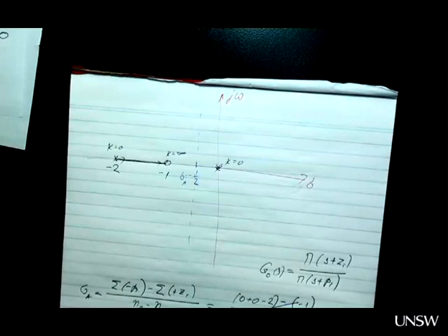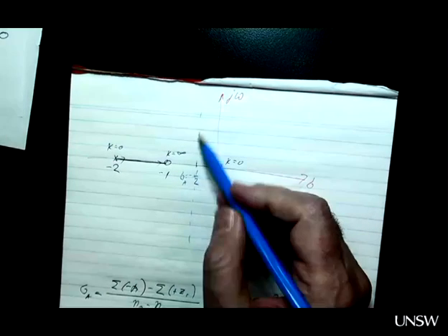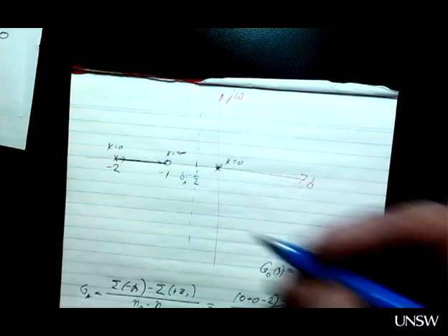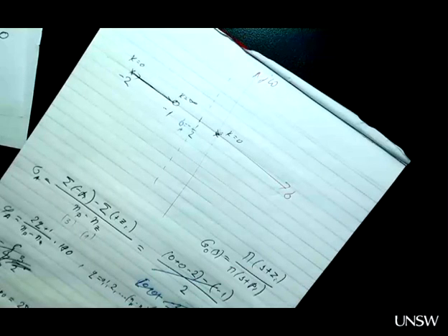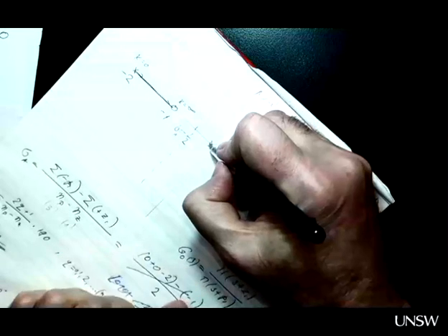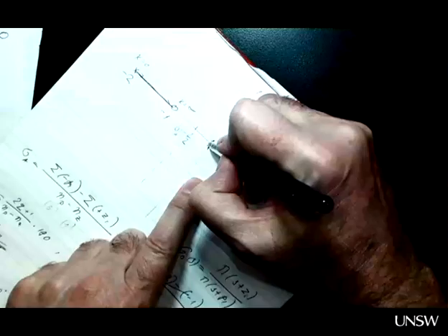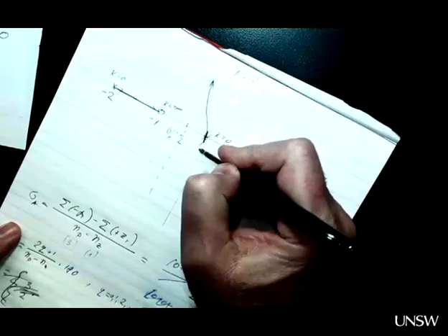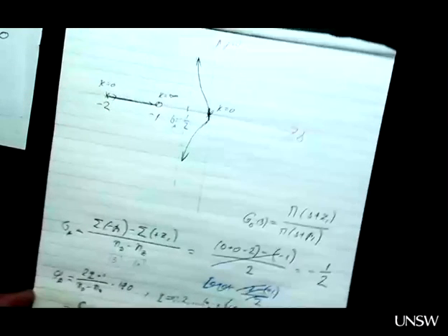So now everything falls into place. You have 2 poles looking for a home, and then you have 2 asymptotes to take them home. Where is home? At infinity. So now it's all up to your sense of aesthetics, which is not something you're going to learn from me. But these 2 poles have to leave the real axis under 90 degrees, and then they have to somehow join these asymptotes and make sure there is a symmetry between the left and right half of your sketch. So this is your root locus.